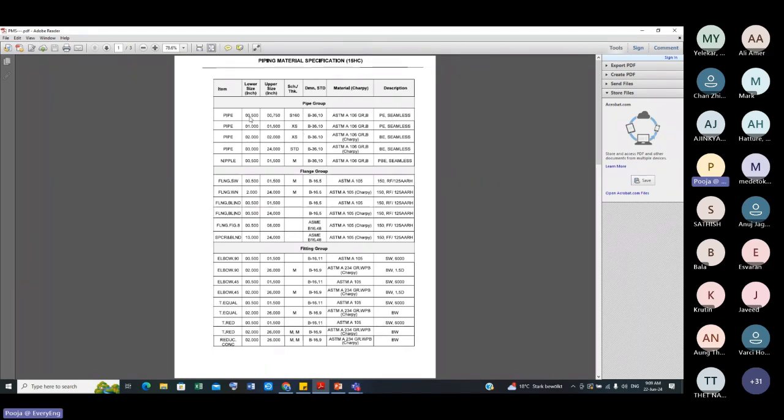So let us say I want to take 1-inch pipe, and I want to use it for the water service. And for water, I can use this pipe. Then this 1-inch pipe with thickness schedule XS. There is another chart which shows, for 1-inch schedule XS, what is the thickness: 1 mm, 2 mm, 3 mm, 4 mm. That's another part.